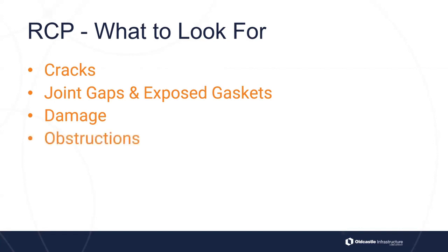We're looking for any obstructions, anything that was maybe in the pipe. I've seen pipe videos where someone came in and punched a hole through it to put either a comm line or a gas line or something through it. So I've seen pictures or videos of pipes where they've had obstructions going through it. I've seen pipes where they've driven the barriers up above, where they're driving the stakes down, and it goes into the pipe itself and causes some damage and some obstructions.